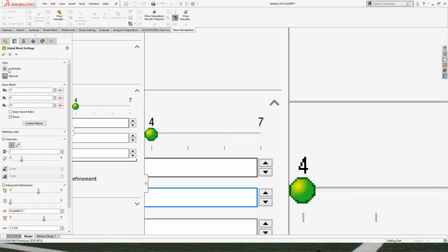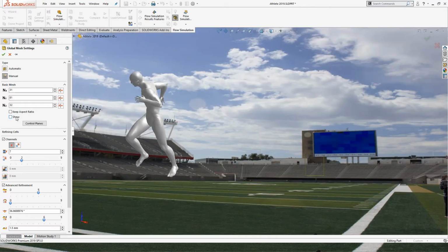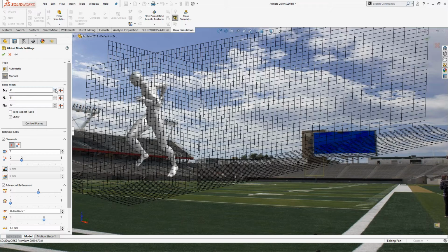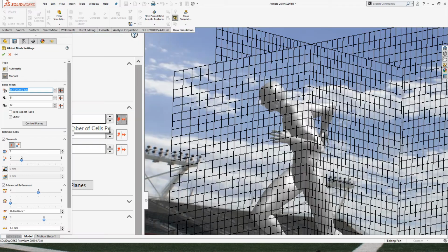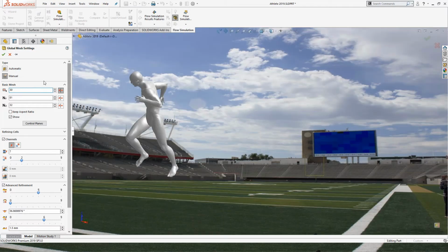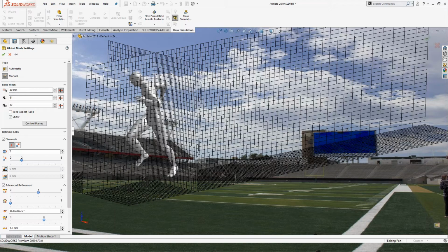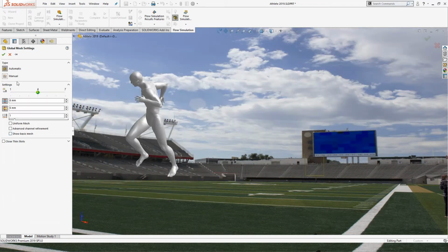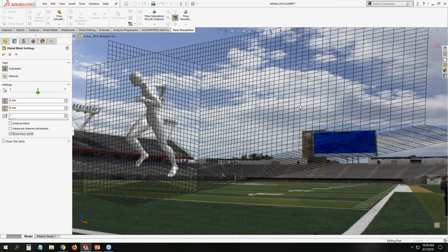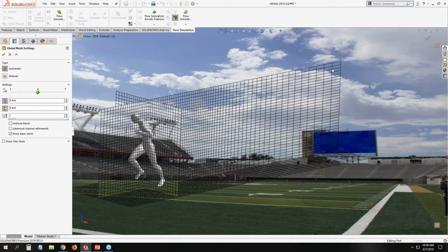But we're not limited to just automatic meshing, right? We can also define the mesh number of cells in a given direction. You can see that changing on the screen in the graphic area, or we can define the mesh size here by typing in a value of the unit. So you can see how that affects that one there. But for most, even for a seasoned user like myself, the automatic mesher does work quite well. Let me zoom out of this. And one of the things that it does, for example, is you can define the lengthening them by defining some value in order to lengthen them further down in the computational domain.